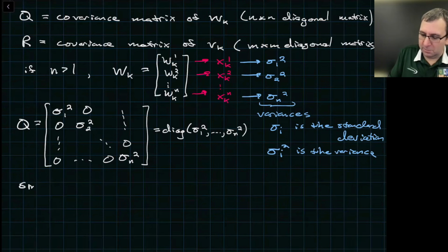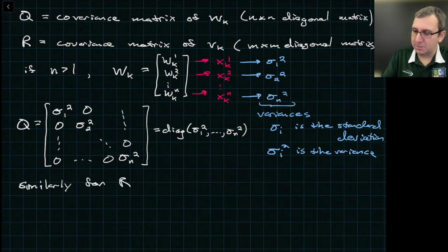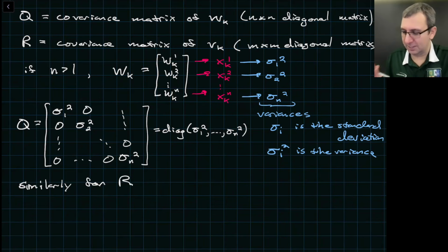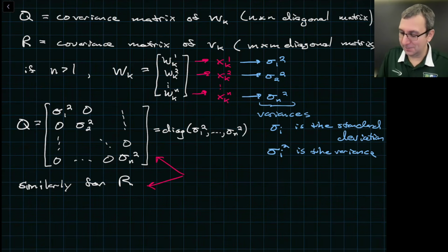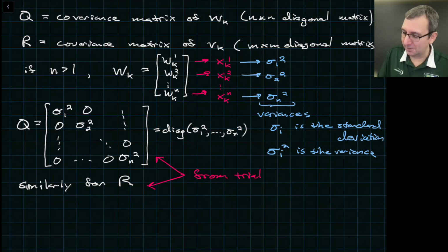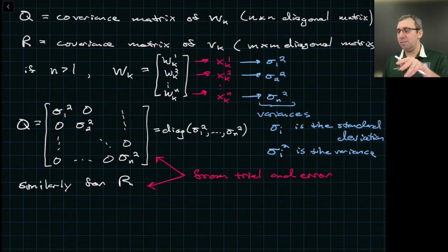And similarly for R, I've said some things about looking at what the sensor itself says is its own error, but often these sigmas in both Q and R are found by trial and error and calibration. Fine by me, right? There are probably other approaches to make trial and error go faster, but really you could just think of those as knobs you can turn.